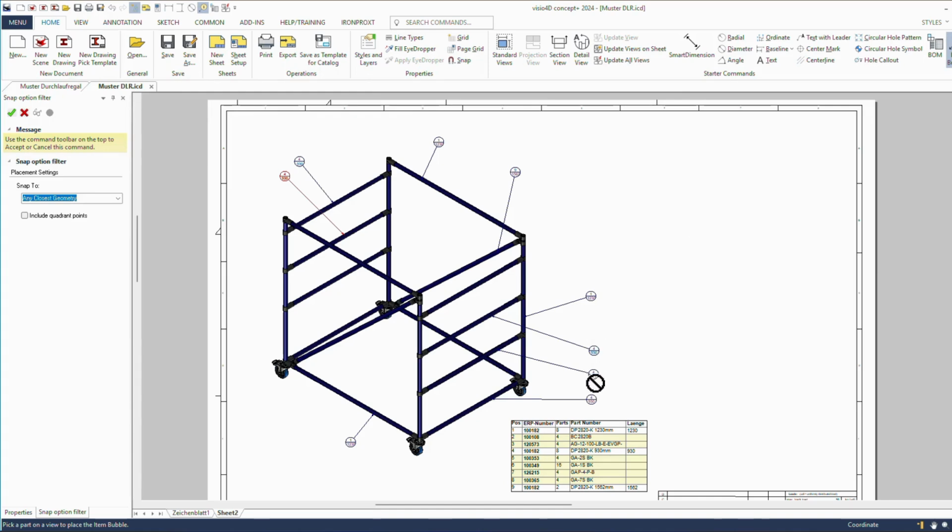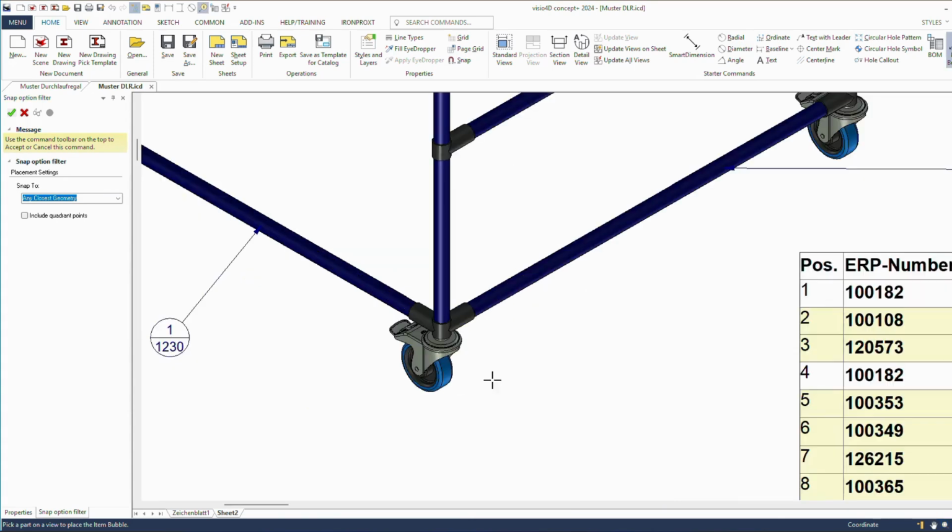I can now position the vertical pipe across, horizontal pipe the diagonal. These are the long goods again. If I now also increase the position number for components, increase the item number, then it will be like this. Only a position number appears here with a question mark below the line. This is because the component has no length attribute. That's why the program displays a question mark. It's simply down to the way the program works. But we also have the option here to neatly extract the joints.